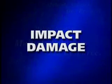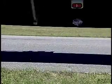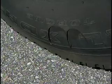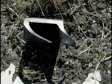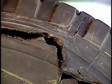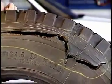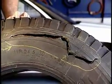An impact damage is the result of an impact with a sharp object under the dynamic conditions of speed, load, and pressure. You will generally see cuts in the rubber from the impacting object, as well as a clean severing of the individual steel cords at the point of injury. Emanating from the point of injury may be a rupturing of additional steel cords in the sidewall if the impact is very severe in nature.